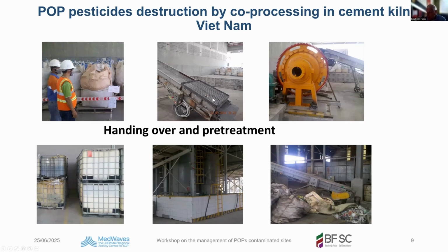It was pre-treated, first over a sieve, then it was ball milled to make a slurry. A ball mill is a mill with iron balls that hit the content of the mill, breaking down the large particles into small particles to be able to make a slurry. The slurry was stored in tanks, and then it was brought to the incinerator. And here waste is also fed to the kiln in portions.